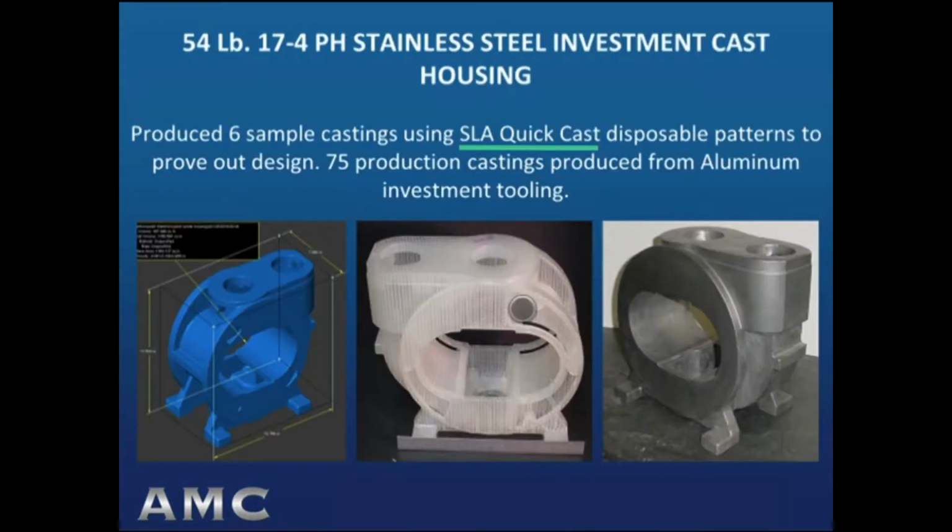So here is a 54-pound, 17-4 PH stainless steel investment cast housing that I produced. It wasn't a legacy casting, but we made 6 of those as sample castings using the SLA Quickcast disposable patterns to prove out the design. And then later we used wax aluminum tooling to make wax patterns in the traditional way to make 75 production castings.